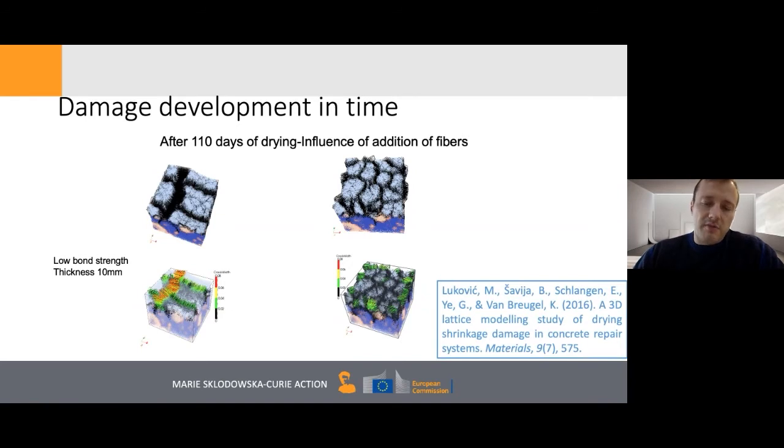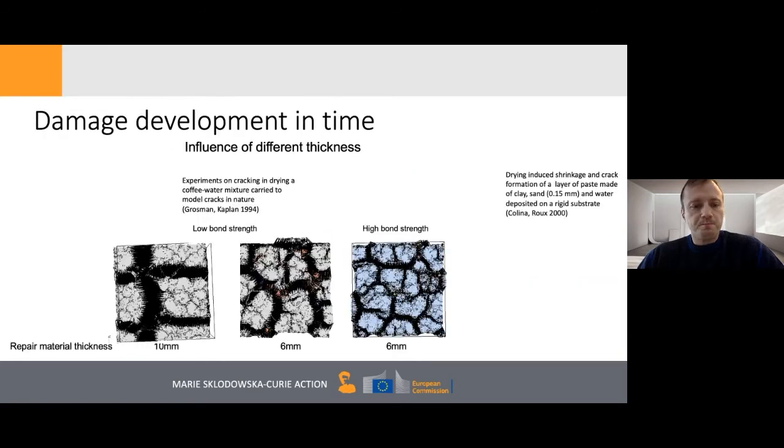So you've also discussed yesterday and a bit today about SHCC or ECC. If you use that type of material, you will have more cracks, but narrower cracks. And this is most of the time preferred in repair applications. You don't want to have very large cracks.